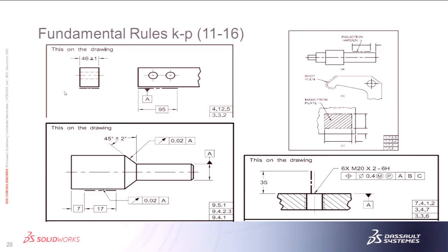So you can do a chain line to say full width of the part, but only on this portion of it. So you can see they dimension that with basic dimensions. Same thing here. So we're looking at the run out only in this area. Doesn't matter for the first 7 millimeters. Doesn't matter after 17, but you need it in that area.